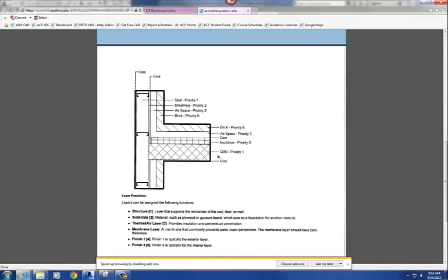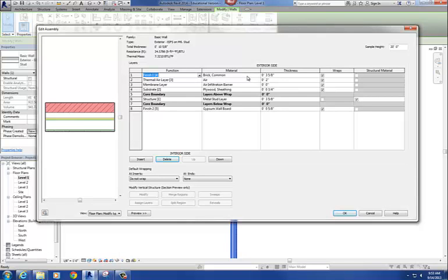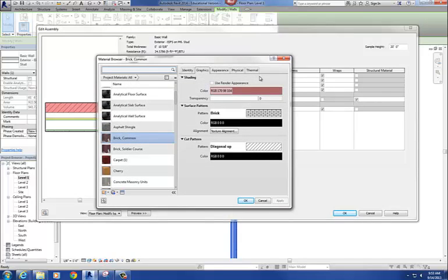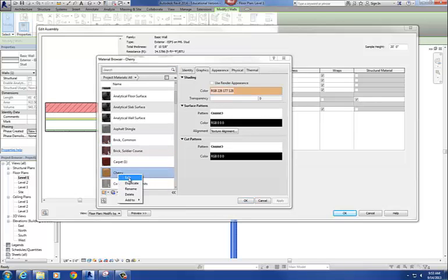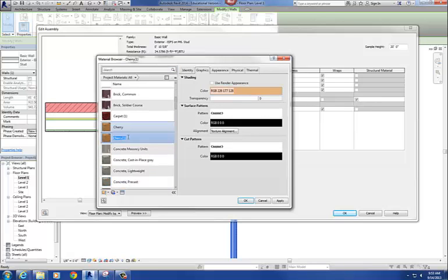All right. Yep. Question. What if you're using non-standard materials? Well, then with Revit you have the option too. For example, you can create your new materials. So if I go to this materials browser, I can create a new material. So what I can do is maybe copy this material. I can duplicate that material. All right, so I got cherry 2, and I can say, all right, this is going to be straw, or straw bale or something like that.